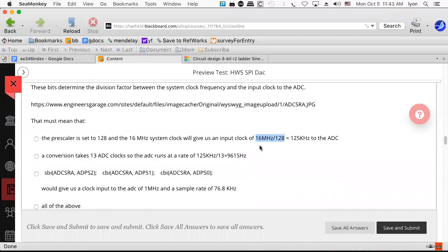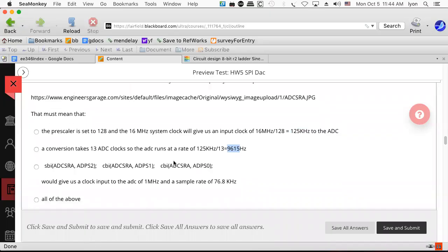So if you take 125 kilohertz and divide it by 25, I think it's like 5K. Yeah, that's 5. So in other words, if it takes 25 cycles first time through with a 125 kilohertz clock, it's going to be doing conversions at 5 kilohertz. That's pretty slow, actually. The second time through, it goes quite a bit faster, probably closer to the 13 clock cycles, which would bring you to a number of 9.6 kilohertz. The first time through, it'll be 5 kilohertz. It'll be slow.